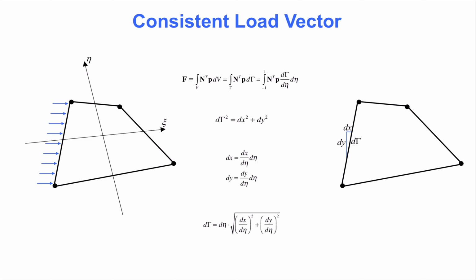For elements like the Quad4, this involves shape functions in a normalized coordinate system, integral transformations, the isoparametric description of the shape of the element, evaluation of the Jacobian matrix and its inverse, numerical integration, and evaluation of consistent load vectors. When you understand those concepts, and when you realize that approximate shape functions make the element too stiff, while numerical integration can soften it, you are well on your way to be a finite element expert.